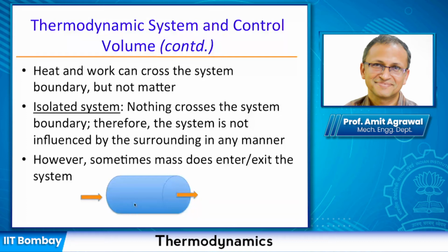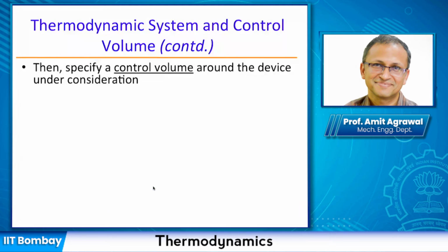So I am going to write down equations for that case. The region on which I'm doing my analysis is my control volume, and I can choose this control volume arbitrarily. I can choose this pipe, I can choose half the pipe; I can take symmetry and say that this pipe is symmetric and therefore I'm only going to take one half of it, and so on. It's like an arbitrary volume that I'm putting, and I'm saying I am analyzing things for that region only. That becomes my control volume, and the corresponding surface of the control volume becomes my control surface.